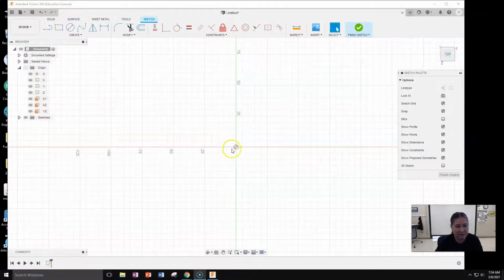All right, so it gives us the origin. We know we're on the origin because if you come up here, let's see if it wants to open for me. It doesn't want to open for me. It'll show you that the point is 0, 0, even if you're back on the main screen. So that's going to be your origin. You like to work there because it locks your sketches in.